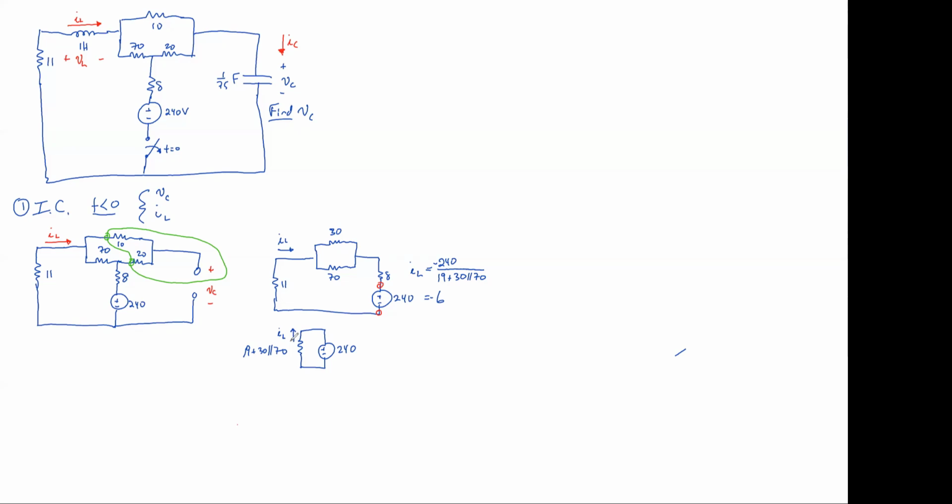And that's the opposite of the fact that we know that there's 240 volts across it. For passive sign convention, you can only use Ohm's law if the current exits the more negative terminal. So we have to modify Ohm's law for this, or we have to modify the 240. We have to say it's either minus 240 if we want to use Ohm's law, or we need to use a new Ohm's law that has a minus in front of it to cope with the fact that the signs are opposite. Just by thumbs up, does that make sense to everybody? Does it not make sense to anyone?